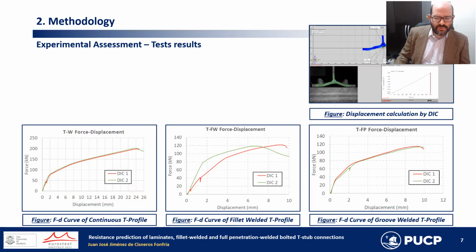Non-linear behavior, force displacement of a specimen, was registered and graphically represented as illustrated. The force corresponds with the one measured by the testing machine, and the displacement is the double of the midpoint range calculated optically, so possible slipping is avoided.